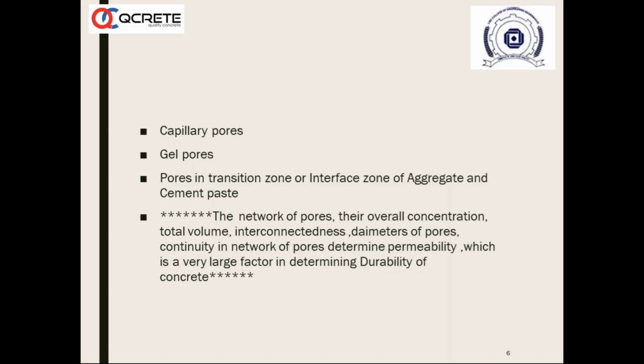Now the network of pores, their overall concentration, interconnectedness, diameters of pores, and continuous network of pores determine permeability, which is a very large factor in determining the durability of concrete.